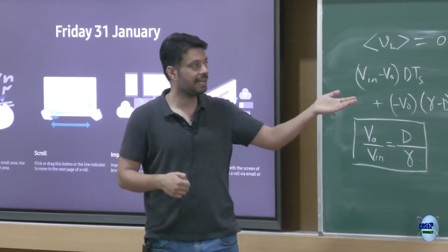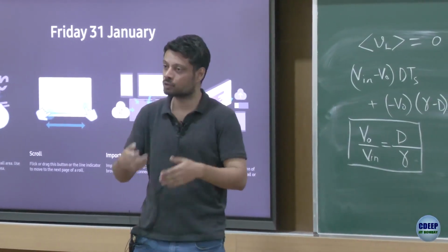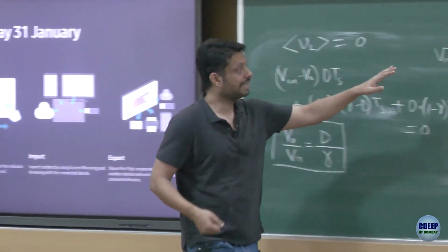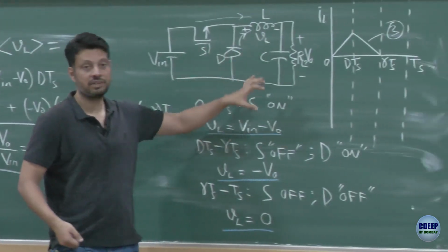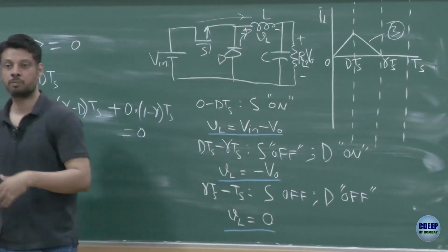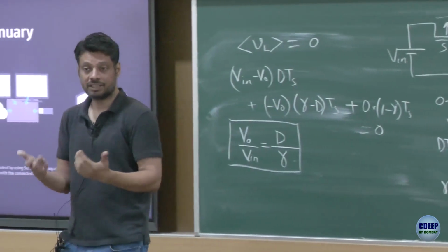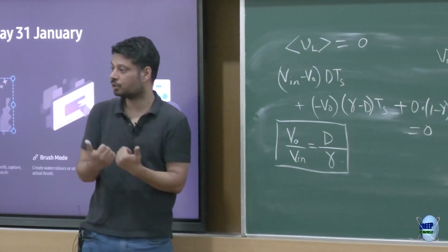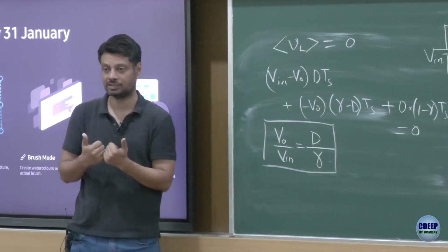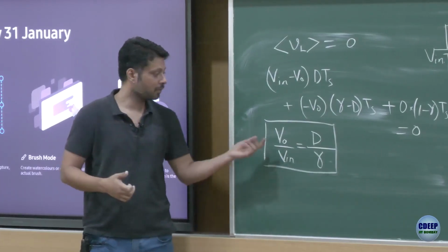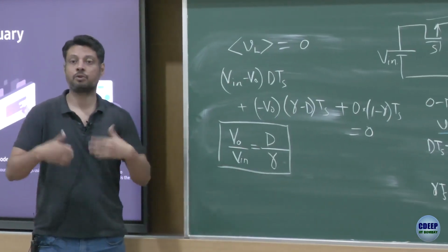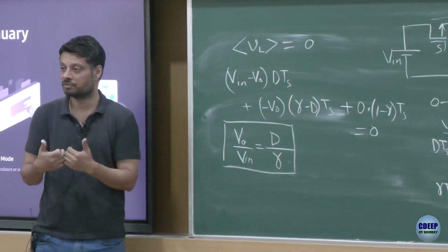And therefore, in reality, all these converters have to have a closed loop kind of operation, where the duty cycle gets adjusted based on observation of the output voltage, right. So if you see the output voltage becoming 60, you adjust the duty cycle, and the relationship is still the same, that if you reduce the duty, the output voltage comes down, thank God, that doesn't change. So it's still the same relationship, but the factors will keep on changing. So if your output voltage goes to 60, you bring it down to 50, right.